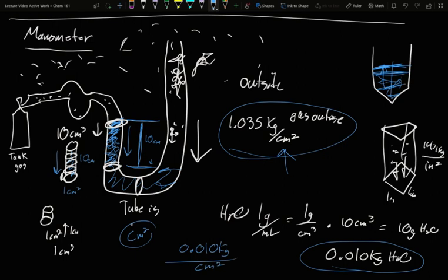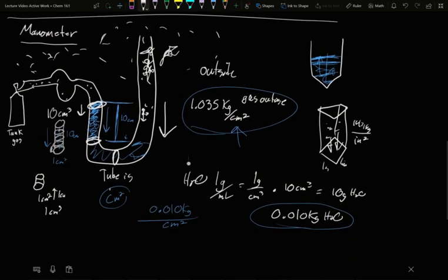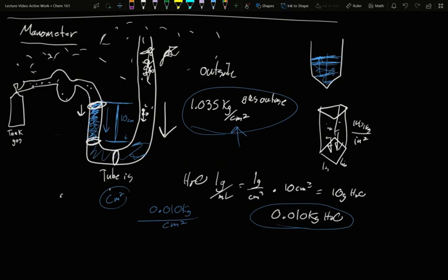It's not a lot in this example, but that is the little bit of extra that it needs in order to cancel out the extra pressure from outside. What this tells us is that the gas pressure on the inside must be that much less. Clear a little of our drawing. Effectively, I still have some gas pressure, so inside gas, and I have some liquid pressure. Well, the inside and the liquid, if my liquid is no longer rising, it must equal the outside.